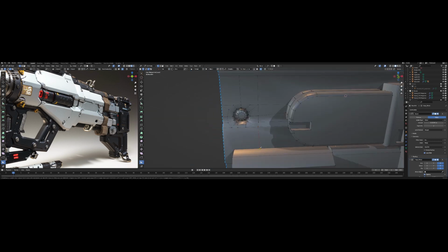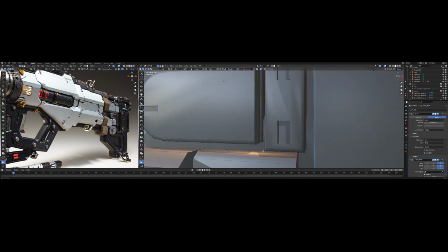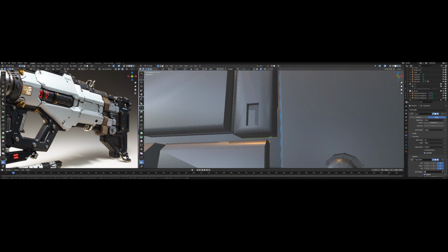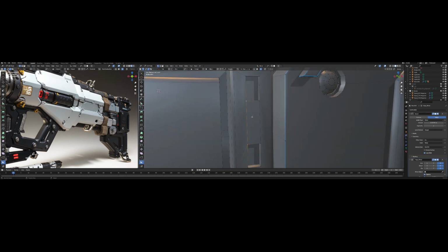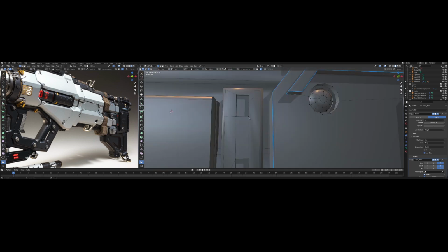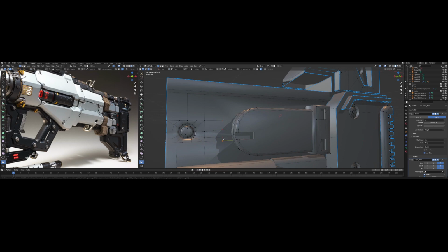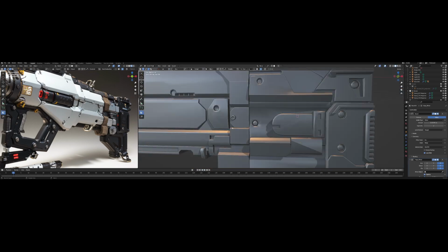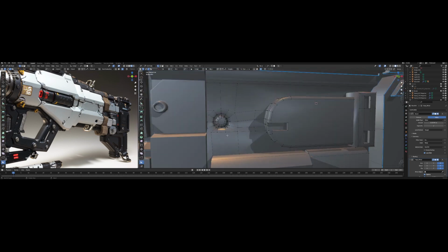If you do automatic bevel weight by clicking sharp, or just change it to 30 degrees, the previously beveled areas that you have fixed or added manually will all be washed out by the automatic sharpening. So you have to do it manually again. It is really time wasting, right?